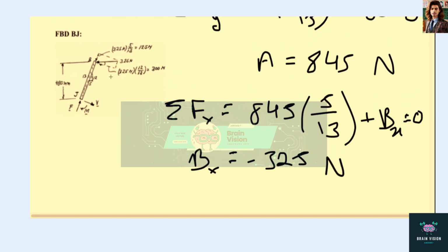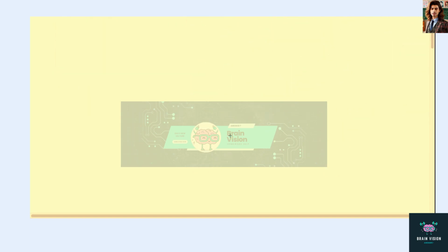Okay, now we're going to use the free body diagram. We know that we have a 325 Newton force here, By, Bx, which means at this angle, you can see that the 5, 12, 13 triangle has been put in again here. So this vertical force along the bar is 125 newtons, and the force perpendicular to the bar is 300. And so what we're solving for is these values down here.